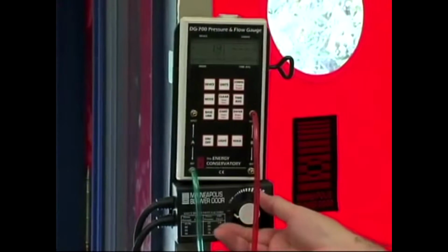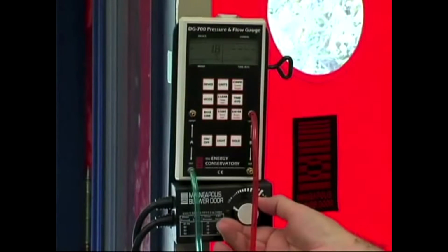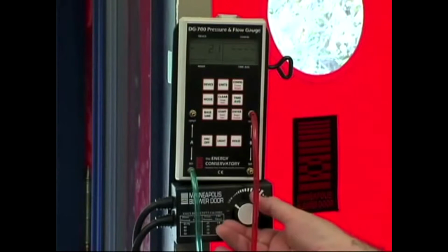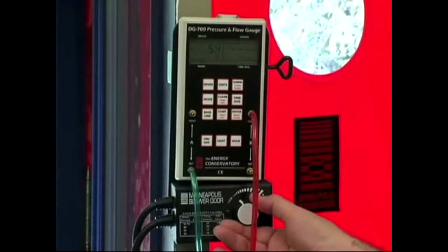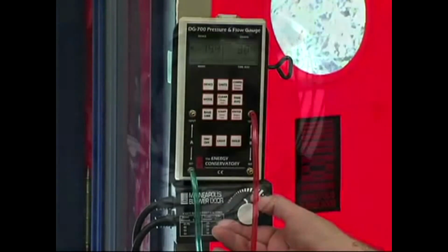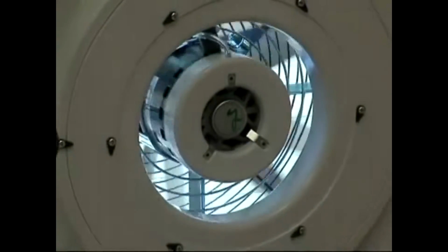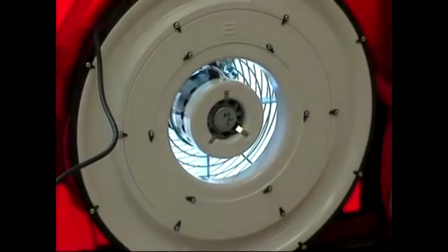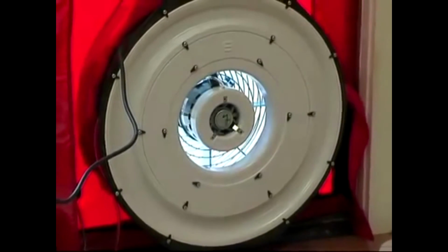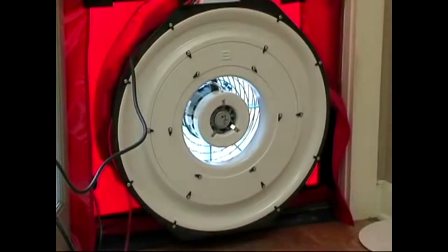Turn on the fan for an initial inspection. Turn on the blower door fan by slowly turning the fan controller clockwise. As the fan speed increases, the building depressurization displayed on Channel A should also increase. As you increase the fan speed, you will be increasing the pressure difference between the building and outside, resulting in increased pressure exerted on the aluminum door frame installed in the door opening.